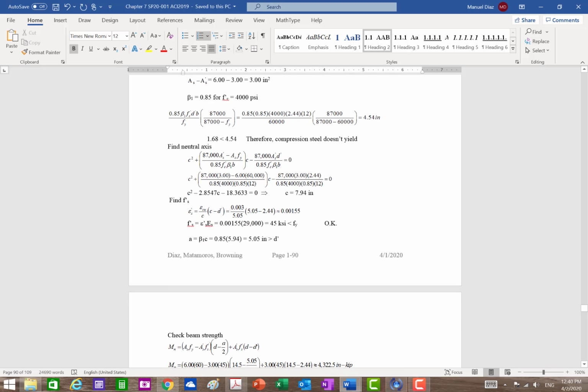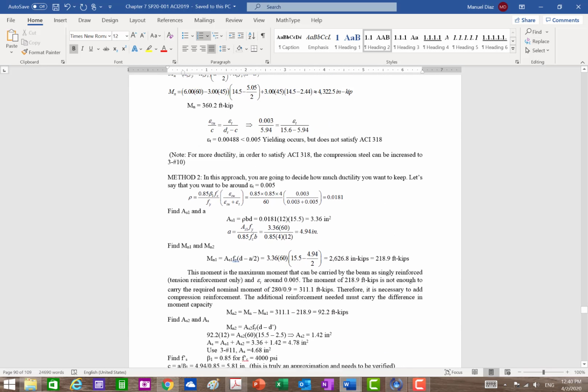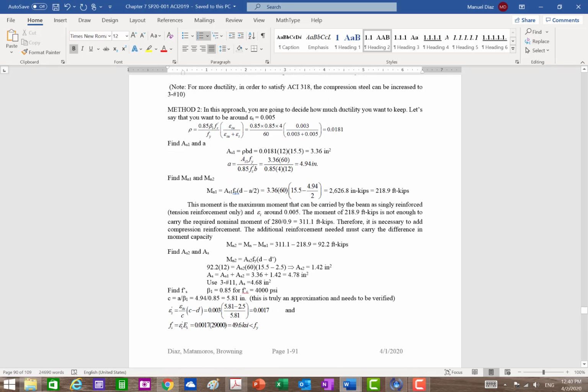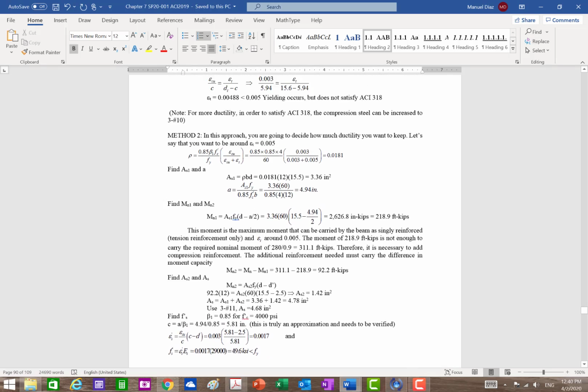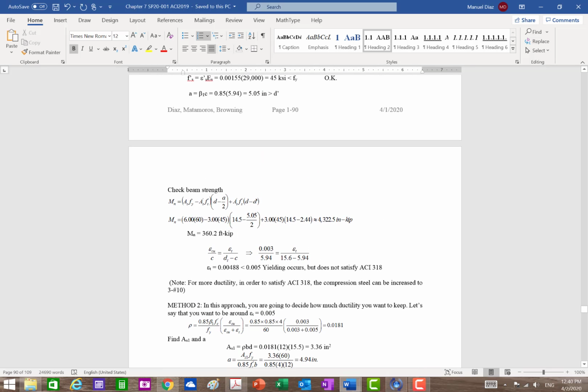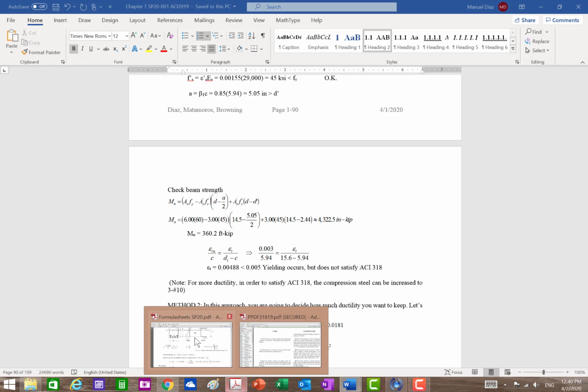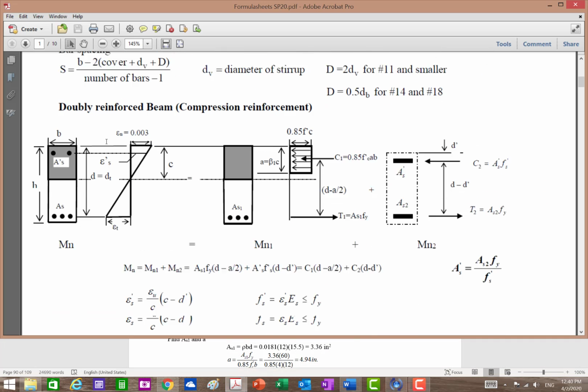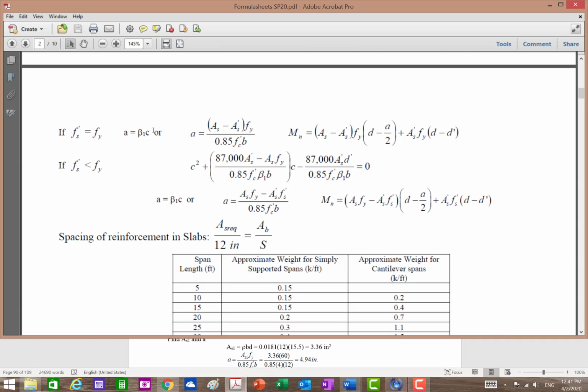Okay. So I got capacity, I got nominal capacity, but my design strength did not work simply because I barely went below the limit, right? So it was a little bit. So 2 options. I can change the amount of steel I put on the tension side because I went to 6 number 9s, right? So let's look at that. That's a possibility, right?